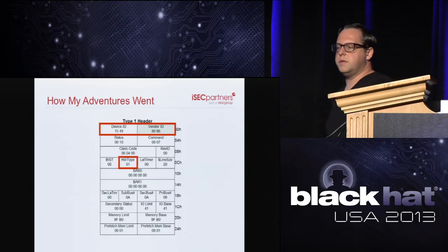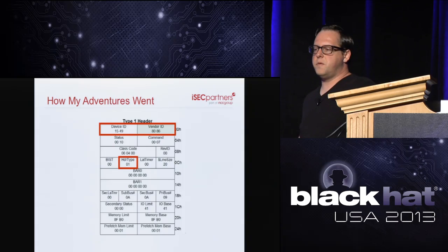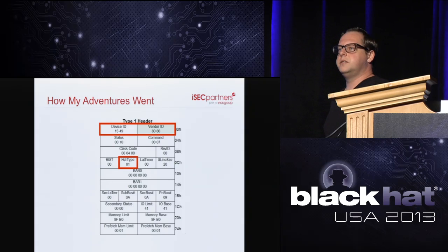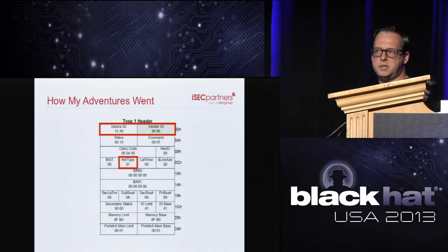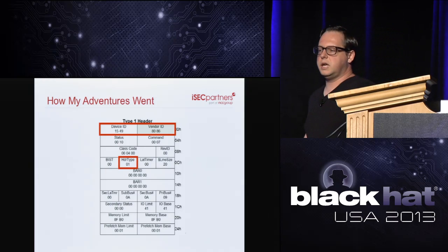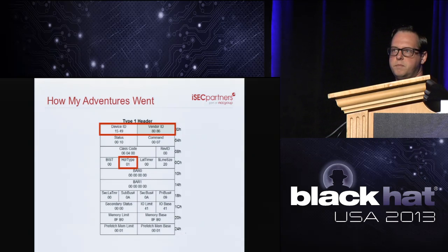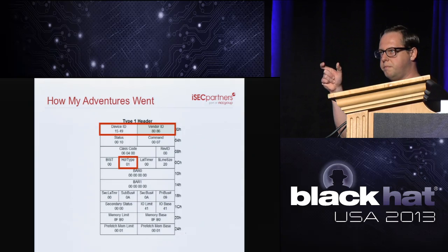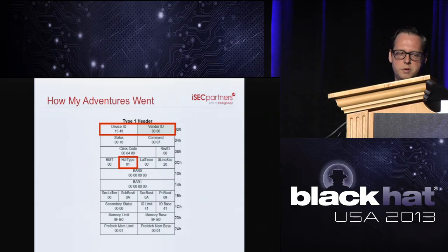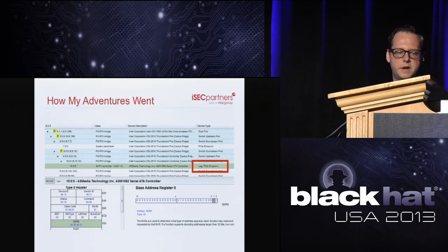Looking at the PCI Express header for this device, we see 1549 8086. Those bytes we were seeing earlier are directly related to the PCI Express implementation. So 1549 is the device ID, and 8086, makes sense, is made by Intel, is the vendor ID. So those chips earlier are those bits that went across the wire. Those are PCI Express identifiers.